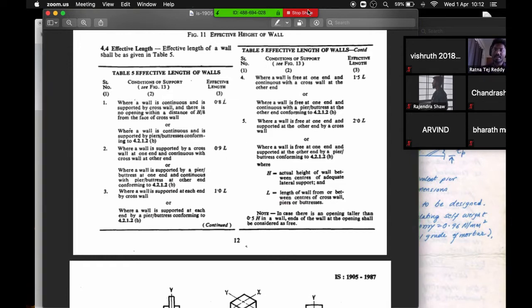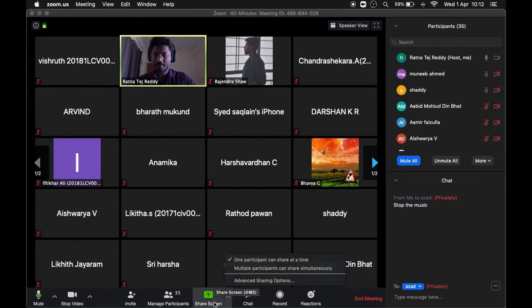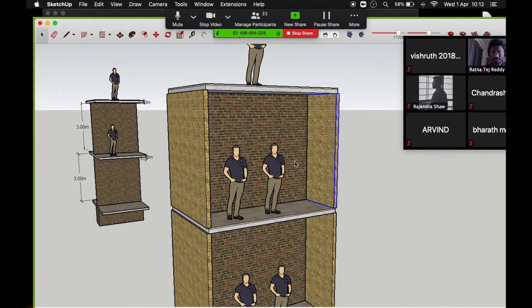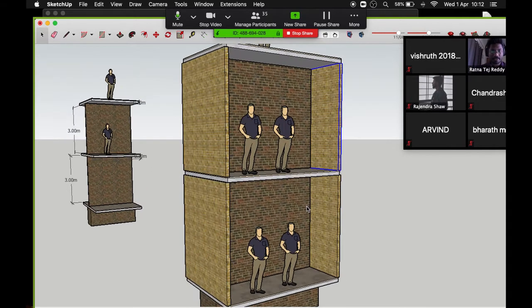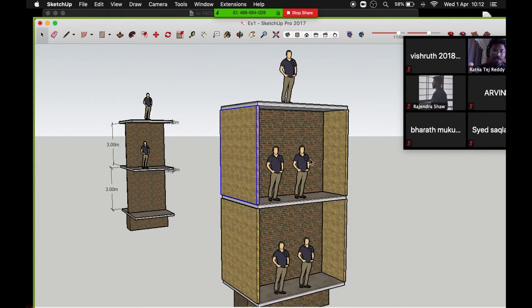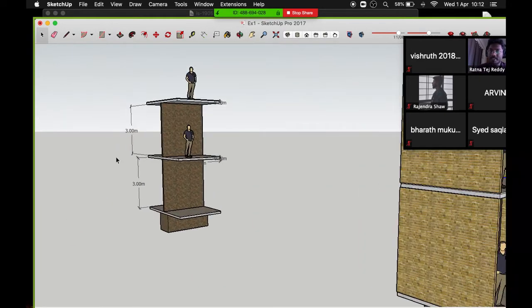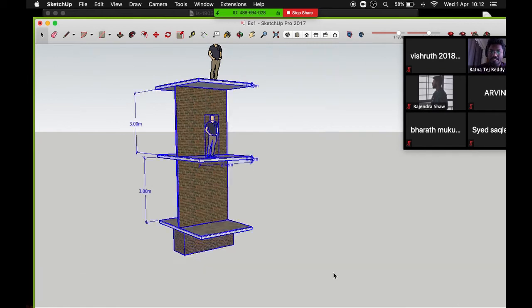You should be really careful about choosing the tables, I mean, what are the tables that you ought to look for when it comes to a particular problem. Since we have lateral conditions and lateral support systems involved over here, we will have to check table 5, that is effective length. In yesterday's problem, we didn't have any end lateral conditions. We didn't have anything that is supporting in the lateral direction. That is why